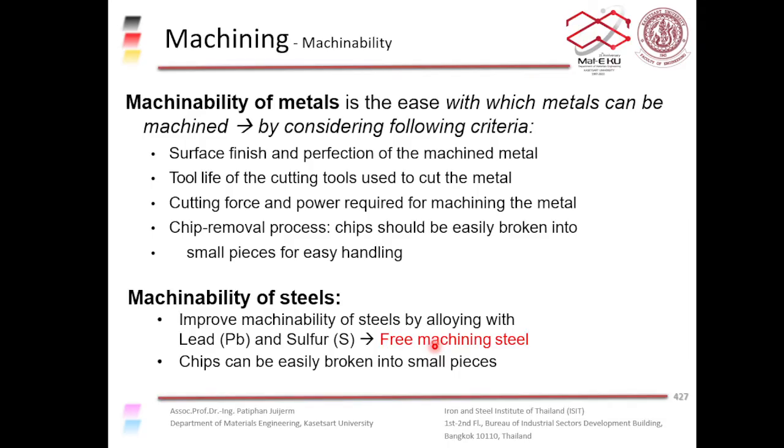If your chosen manufacturing process is machining, like milling or lathe turning, you have to choose the material accordingly. You might have to choose free machining steel, so steel with added lead and sulfur. But if you choose another type of steel, it will be more difficult to produce the workpiece. Or the other way around.